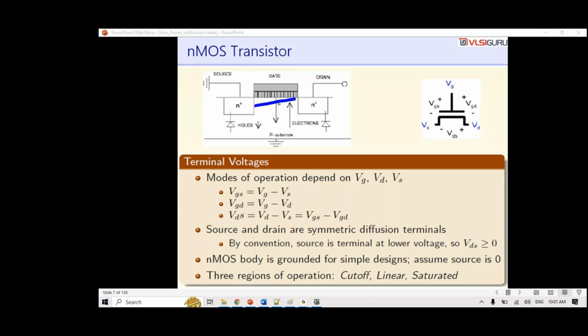The channel gets formed, okay, which at one point when it reaches a point where enough negative charges are accumulated, when enough electrons are accumulated here, they are attracted, okay, because you are applying a positive voltage, it becomes some kind of capacitor kind of circuit. Because one side it has got a positive charge, it will attract the electrons, and then this channel gets formed. That's a very basic thing. So when that channel gets formed, because of the voltage difference between the drain and source, and you are establishing this channel, the current starts flowing from drain to the source, okay.